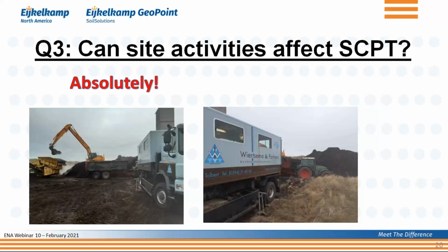And therefore, you're going to have a major problem, a major issue, because we're creating a wave in the soil by hitting a sledgehammer. But if you have a heavy vehicle going by, or if you have some material being dumped on the ground, all that creates a wave as well. And those are being recorded by these very sensitive sensors as well. And then it's going to be very difficult to analyze your data. So you need to make sure that if you have site activities, you either stop your data acquisition, wait until the tractor, in this case with the trailer, has gone by, or you basically ask those people to stop their activities while you do your seismic CPT.